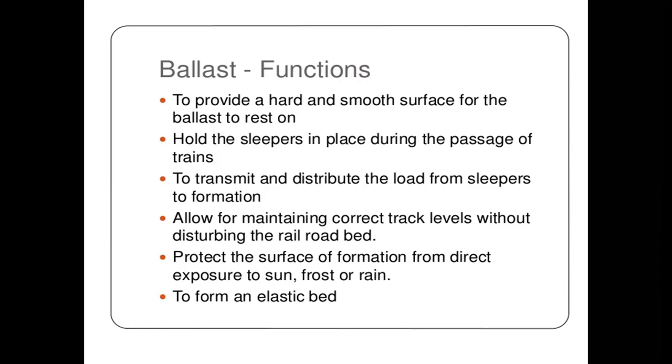The major functions of the ballast are to hold the sleepers in their position while trains pass, and also to transmit and distribute the loads from the sleepers to the formation bed.